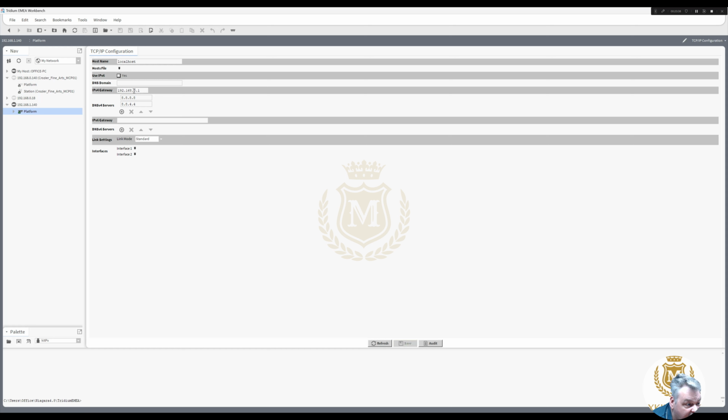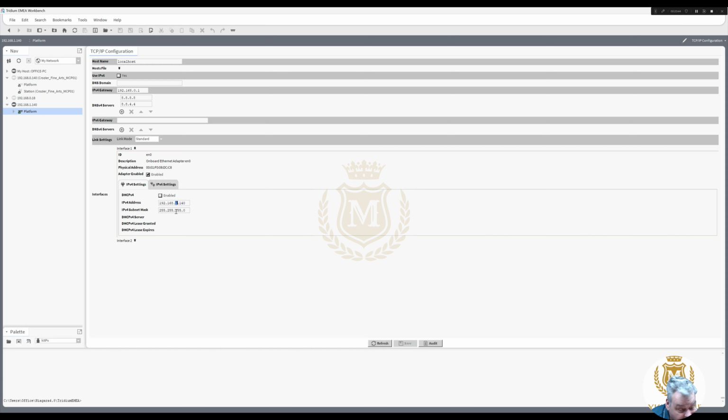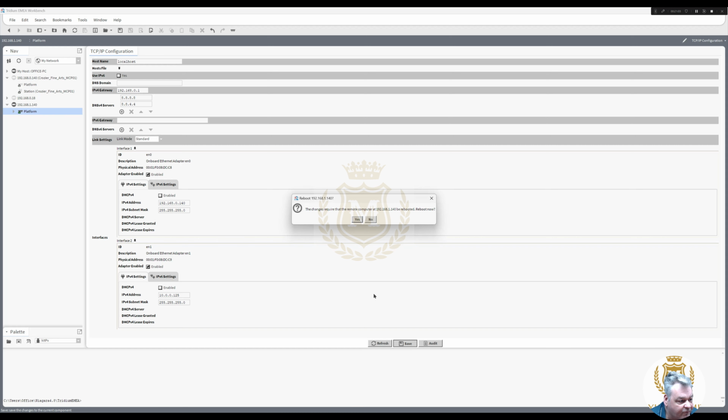I've used the gateway 0, but when you see here, it's force of habit because I always use the default for the JS8000, which is 192.168.1.140, but I'll put that back to there, and of course we've still got the 10.0.0.125. So this is going to reboot itself again because I've changed the IP address for Ethernet 0, the primary Ethernet port.